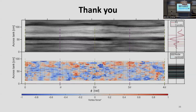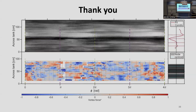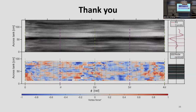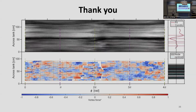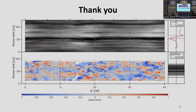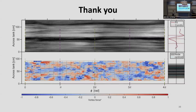So I don't know exactly if there's a study which looks into what the capillary wave does to the turbulence spectra. Just the capillary waves, because they are almost of similar size, similar length scales. But the gravity scale wave does not affect the turbulence spectra, where in the inertial subrange, it mostly is concentrated towards lower wave numbers or larger scales.